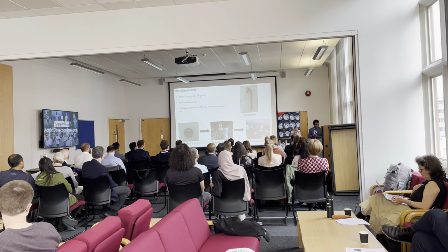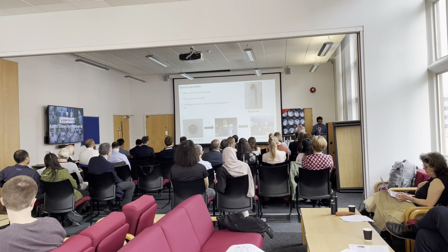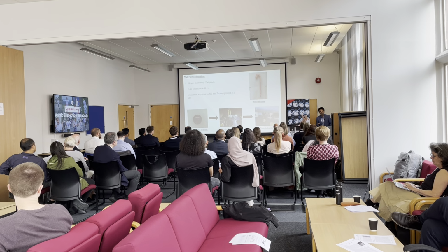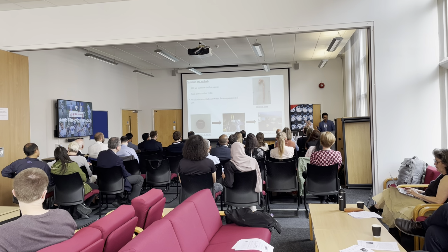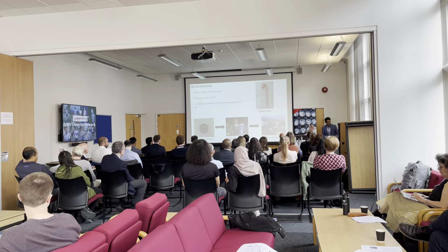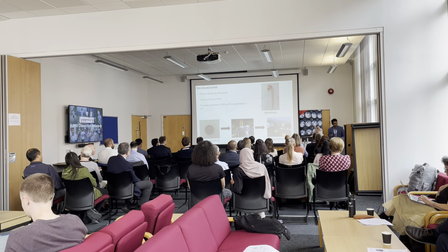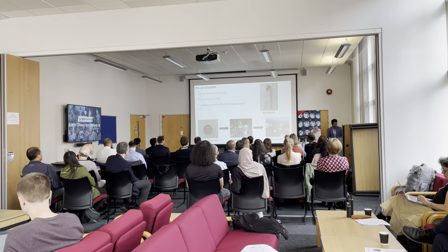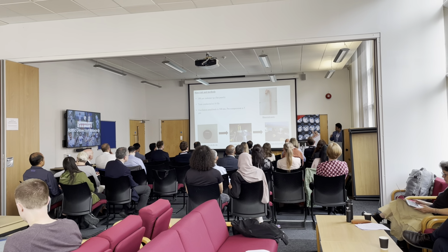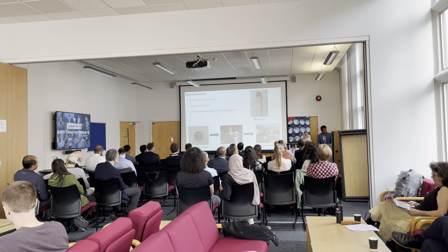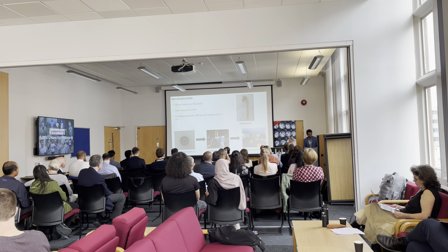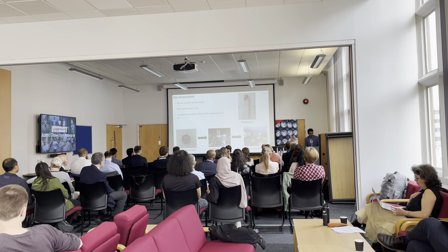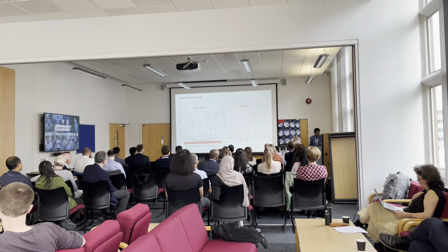All the tests were conducted at 10 Hz, and the frequency was gradually increased up to 110 Hz, which is the resonant frequency of this particular actuator. The oscillation amplitude was around 500 nanometers, which is 0.5 microns, and the pre-compression was around 5 microns. So the process was we obtained some of these rectangular samples, placed them in the rigs, selected the indent points, in this case 3 indent points, and then performed the nanoindentation.